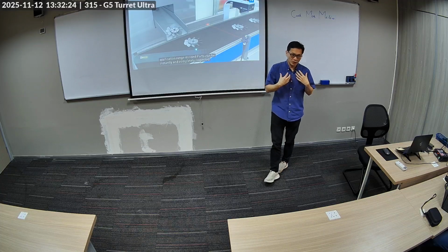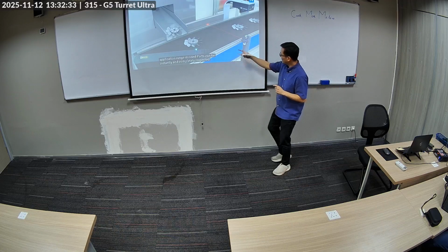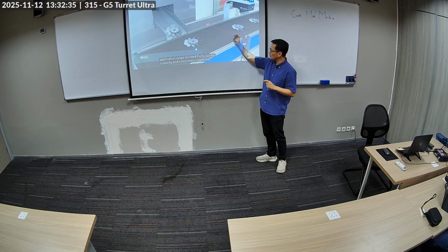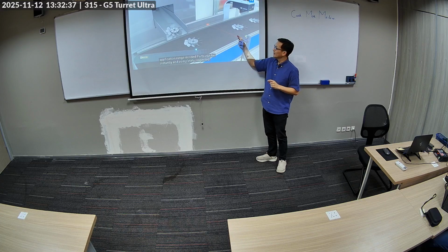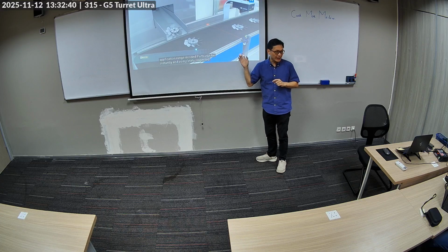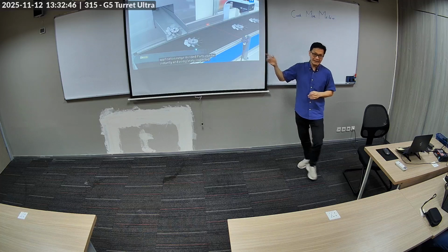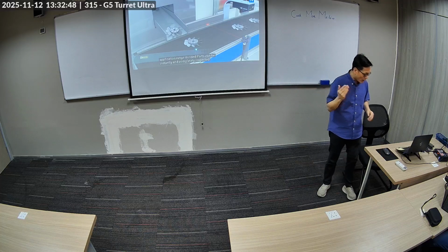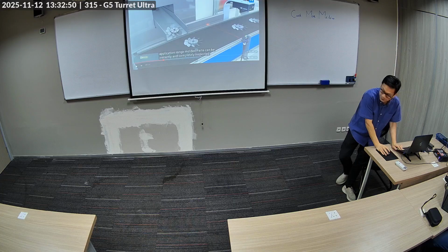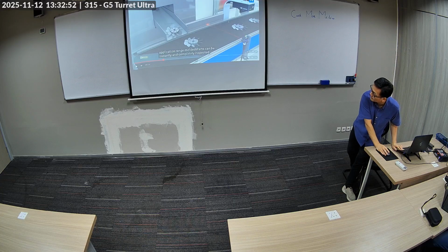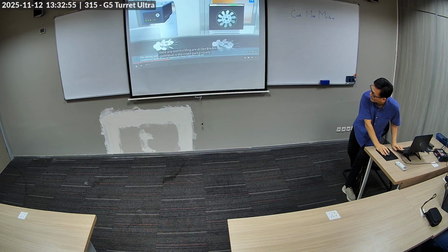If you're the camera, what do you need to know? Position, right? Like, when am I supposed to take the picture? So, if this passes and trips the laser, and you know the speed of the conveyor, then you know when you should take a picture, right? So that laser is there to time when you're supposed to inspect. Good.